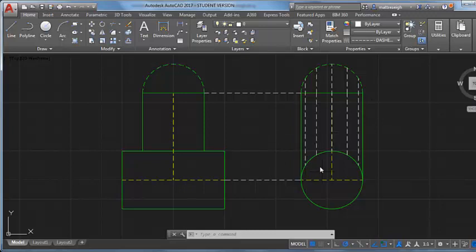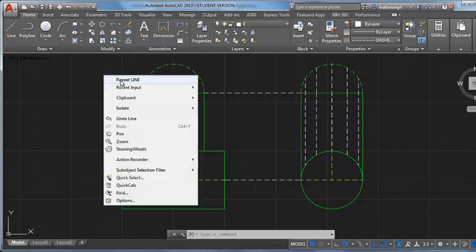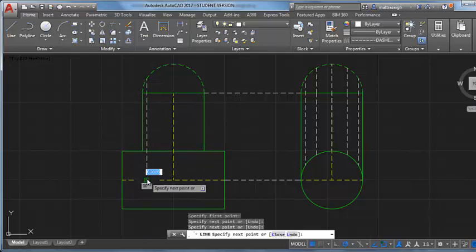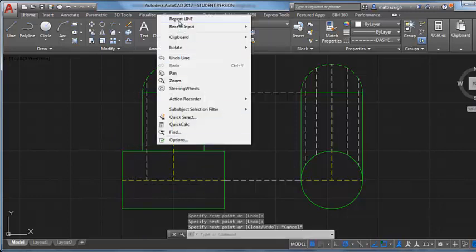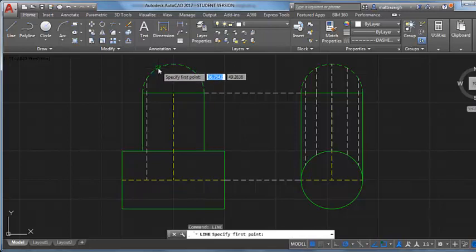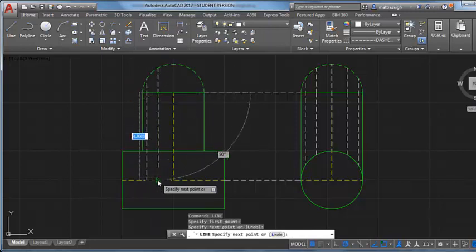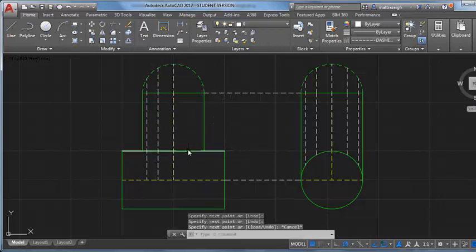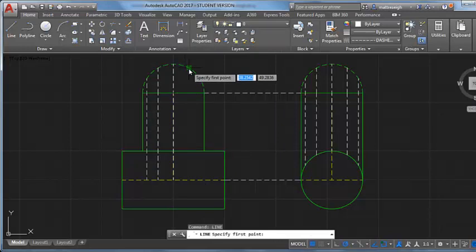And now I've got that information that I can project across and do a grid pattern here to block in this V here. So let's continue and bring these ones down. And what I'll do is I'll just bring these down long, and then I'll tuck them where they actually stop with the information from the right side view there. So I'll actually bring this one down all the way. Okay, kind of covering up my center lines there, but that's all right.